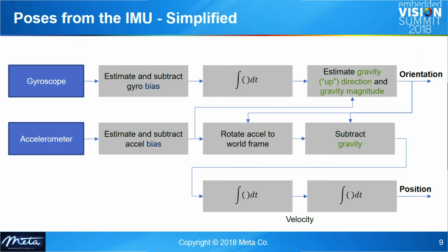As I think you might be able to notice here, this won't work in practice, mainly because of this double integration. Even a small, very brief moment of incorrect readings from the accelerometer, because of the double integration, ends up leaving the system state in constant linear motion.